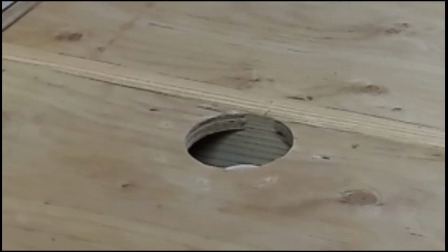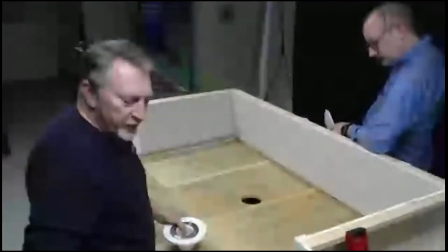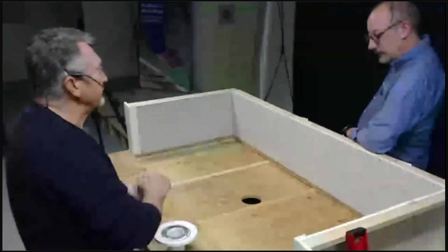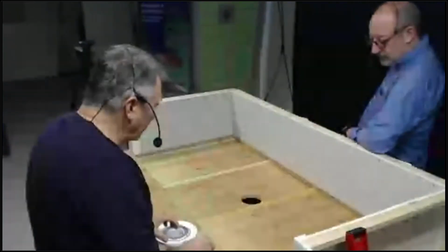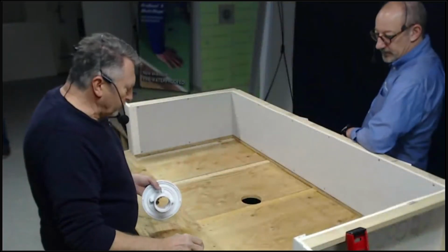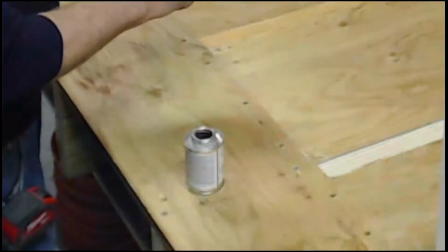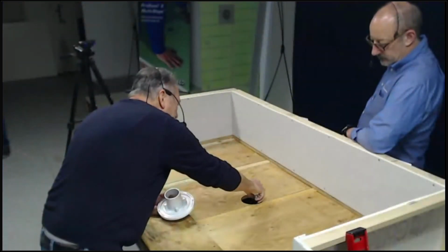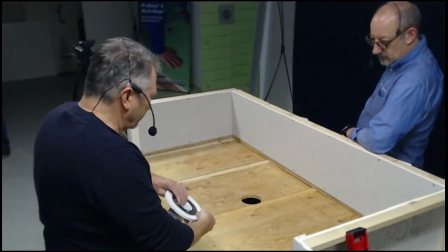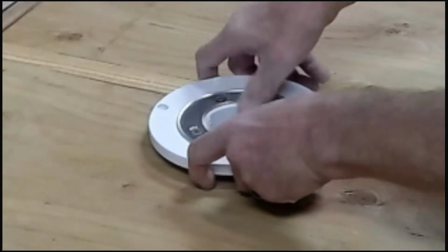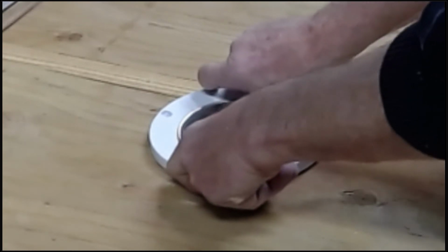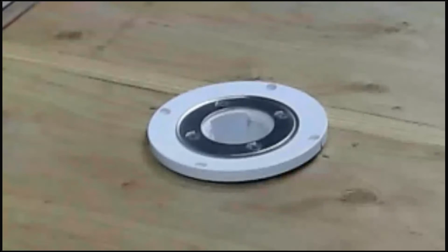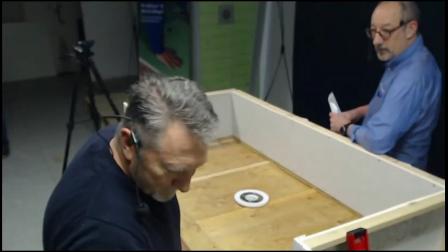Okay. So now we're ready to go ahead and actually glue the drain into place. Obviously, your stub would have been glued already. I'll just put some PVC cement on since it's a socket weld on the pipe, and then simply put it in place, and down it goes. Obviously, you would normally use purple primer with this, but for the sake of me, you didn't, because I'd look like a Smurf.